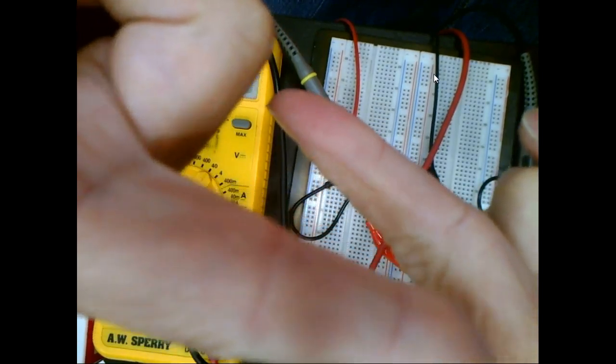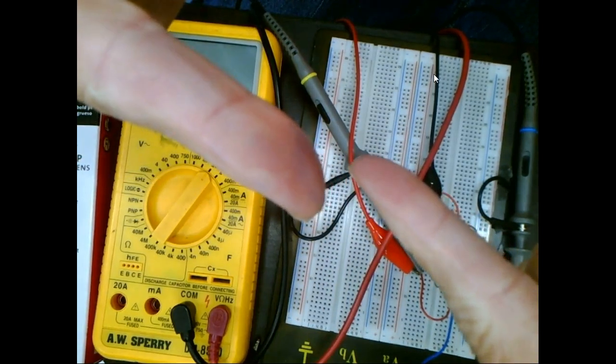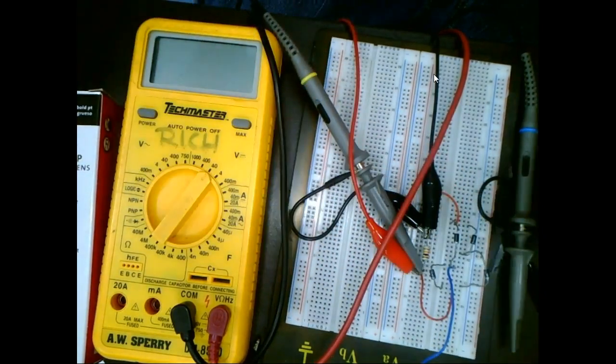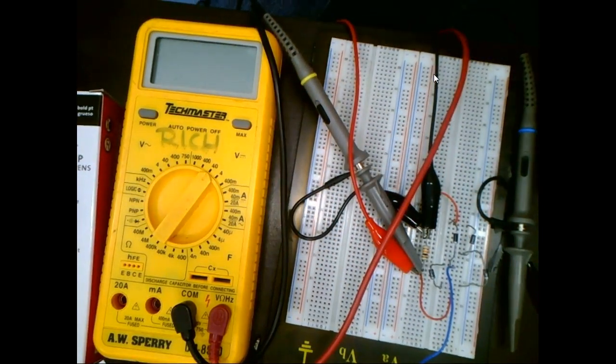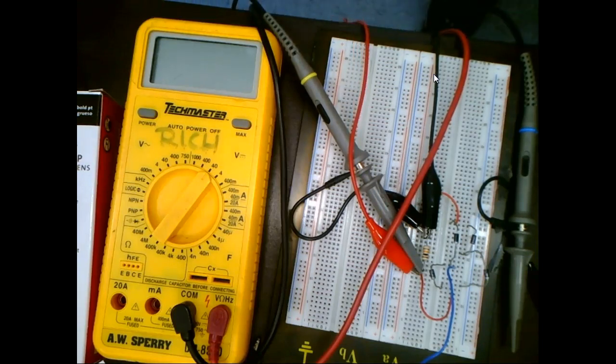So if I come over here, my capacitance would go up, right? You understand that? If I do this, my capacitance would do what? Go down. So we do it one of two ways. We either adjust the size of the plates just by sliding them over each other, or we adjust the distance. So we just have a little screw that we adjust, and it makes the plates either closer together or wider apart. And then we have the insulator.